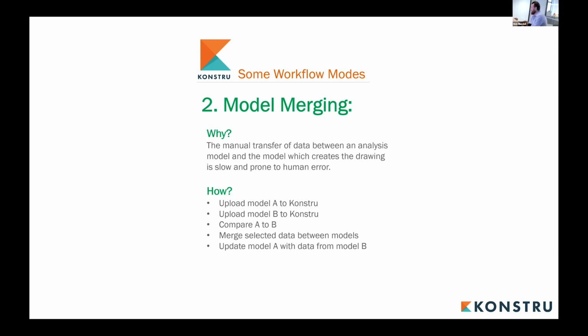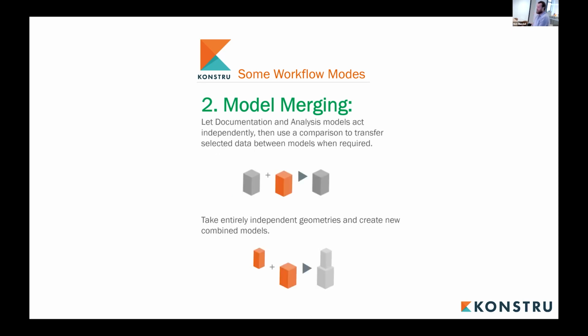For a software like RAM, this usually means information such as studs, camber, profile, etc. And our goal here is to be able to compare two models and then extract information from one and add it to another. The demonstration I'm going to show is basically allowing metadata to move from one model to another.